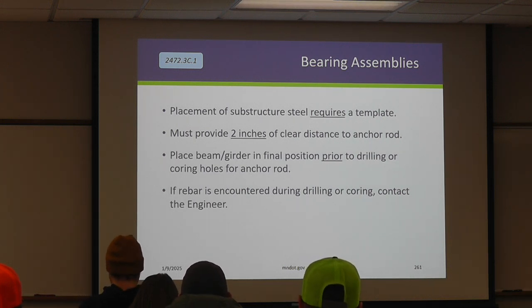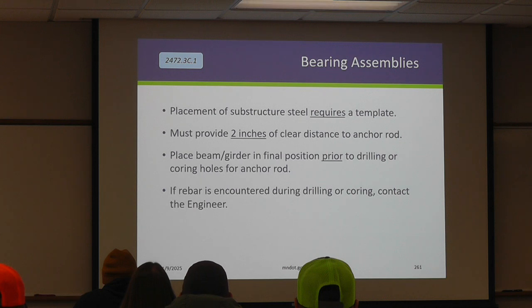You want to make sure that the girder is in that final condition. Again, we allow them to move it a little bit. We're pretty loose on our girder placement tolerance, but keep in mind that if you let them move that girder 2 inches over, and we said you have to have 2 inches clear, you're probably violating that if you installed it from a template, right? So if that rebar is encountered during drilling and coring, you have to contact the engineer to figure out what bar it might be and what the next mitigation effort is.